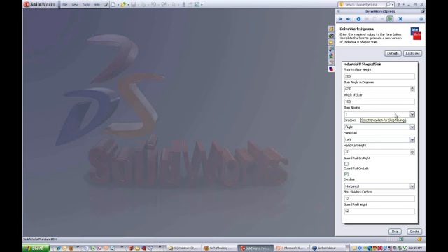The step nosing is a simple drop-down box. Once again, limiting the data you can select from. Give it the maximum value. Next two fields define the direction the stairs turn and what handrails are required, again with drop-down lists. So we'll go to the right and we'll have handrails on both sides.